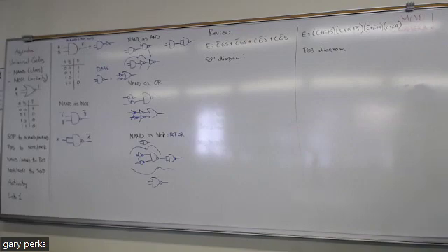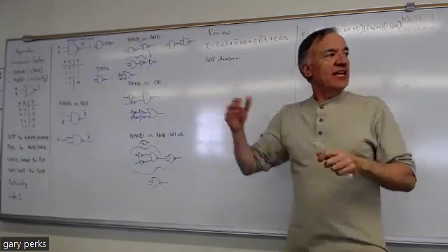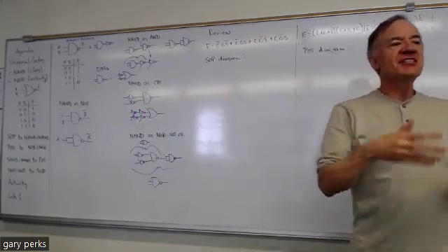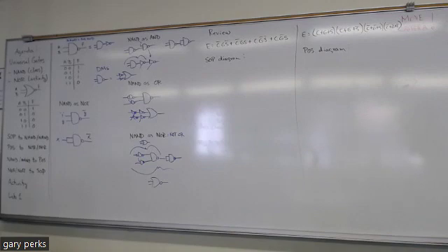You see the big silicon nugget thing. At the silicon level, it's useful to have one gate for your entire circuitry, because then you only need one image. You know how they use the photo tool and they shine the UV light to harden the photoresist, and they etch it away and all that kind of stuff. Well, if you only have one type of gate, that's only one kind of image, right? It's not like several images. So again, it leads to lower manufacturing costs.